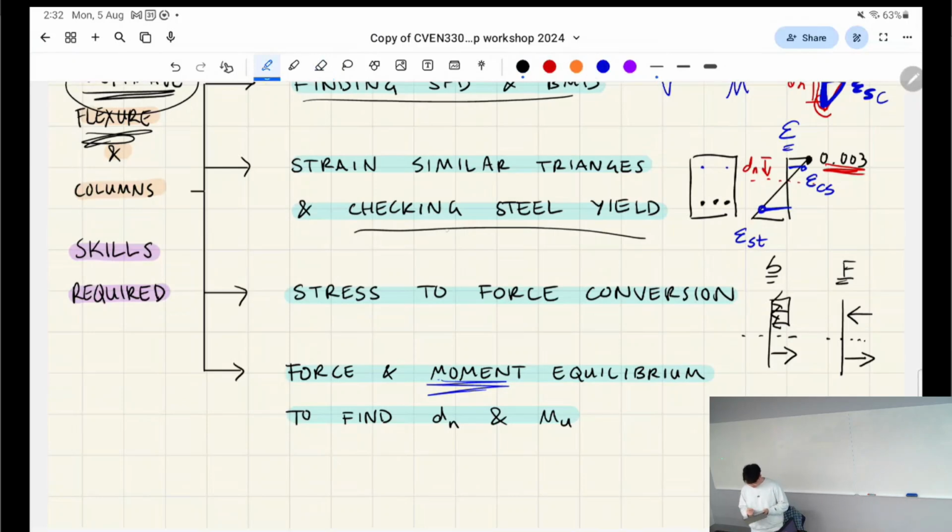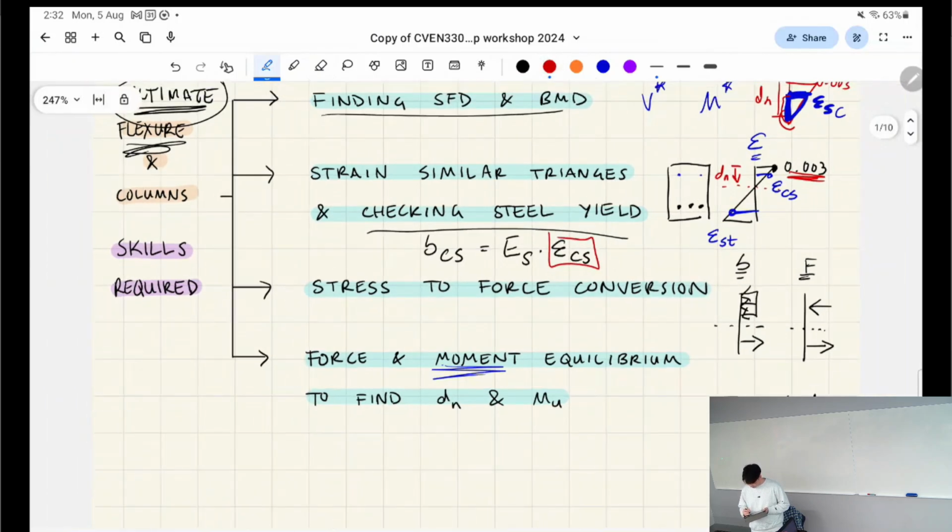The other formula for converting the stress in, for example, the compressive steel, involved using the elastic modulus and then finding the strain of the compressive steel. And the strain of the compressive steel came from similar triangles. Do you know what I mean? So these are all fraction equations, but when you add them all together, it starts to look confusing. You do enough practice though, and it all starts to come together. Okay.